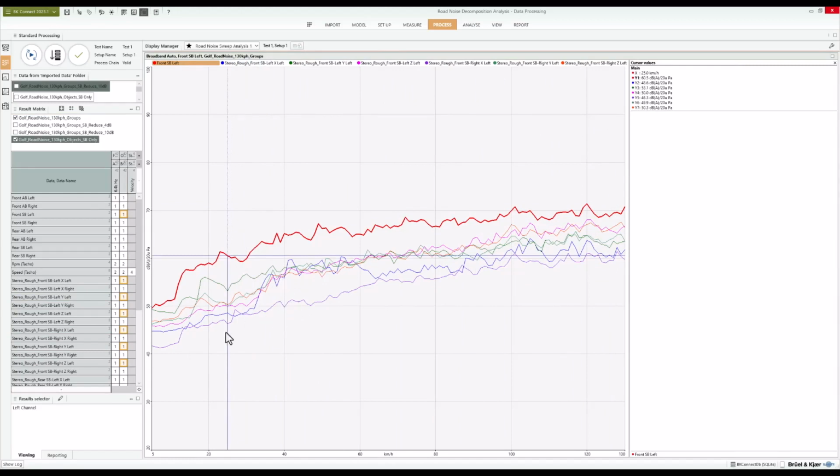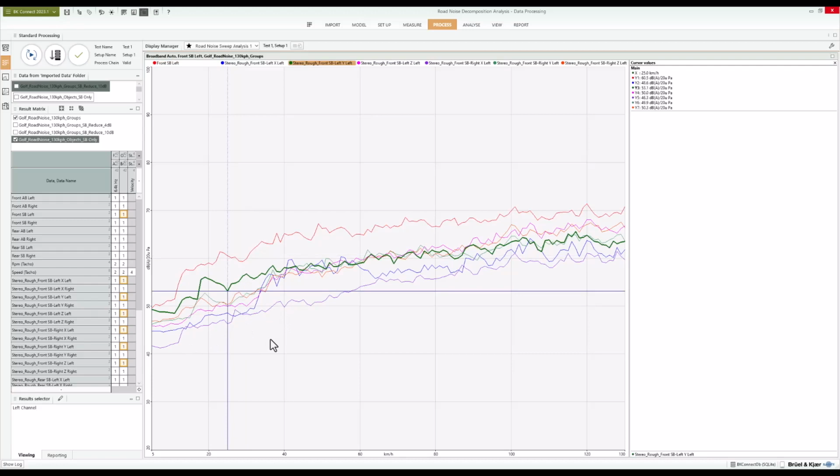If we break this down by speed range, in the lower, kind of below 40 kph, we've got this one standout, our front left corner in the lateral direction. That's the Y direction globally on the vehicle. It seems to be dominating there. That could be something we go back and look at in the vehicle design, see if there's something we can do to improve the contribution from that. Maybe there's a sensitivity resonance in that direction to be able to reduce the overall level in that range.